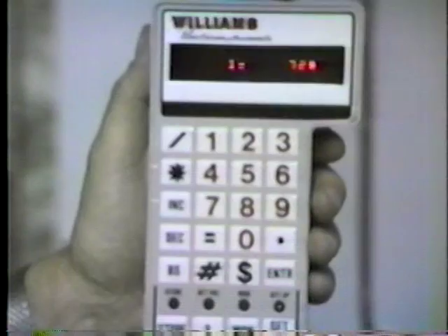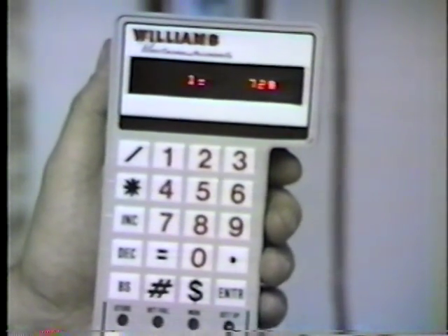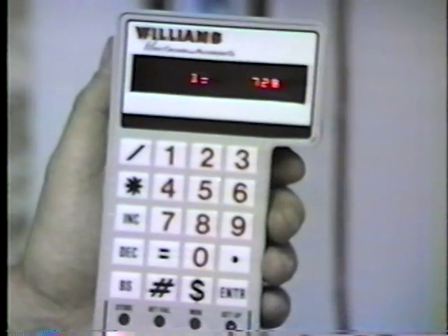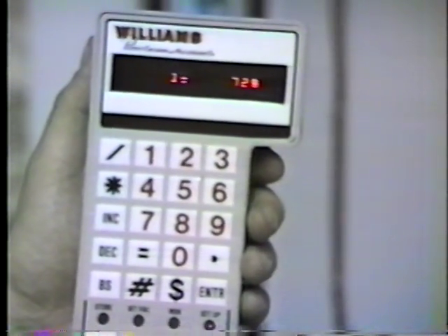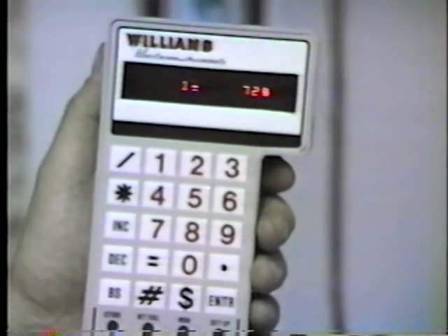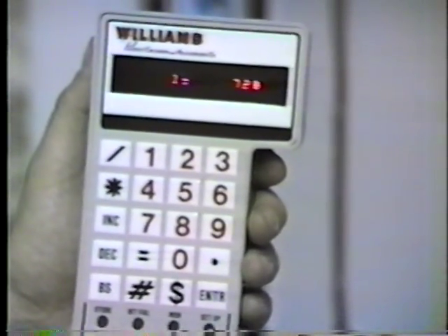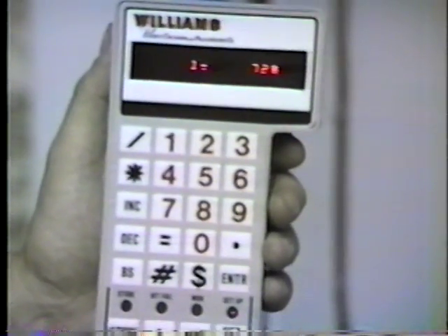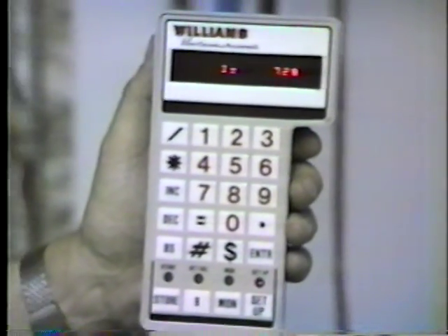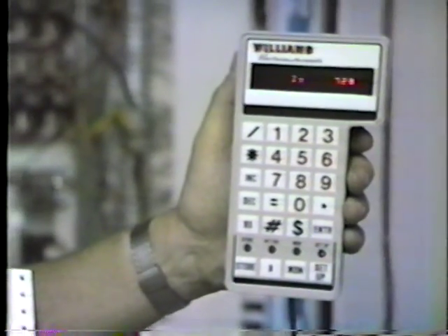Item terminal address number 1 says maximum operating mill speed. And item 2, maximum operating mill, minimum was first, maximum second. All right, let's take a look at the handheld now. That shows you the value that we set in there, and that's the value that we want to keep in there at all times. The 72% represents the starting position for your roller mill. That's the minimum position, not necessarily the minimum that the roller mill will operate, but the minimum point that we use to reference some of the other parameters we're going to set.